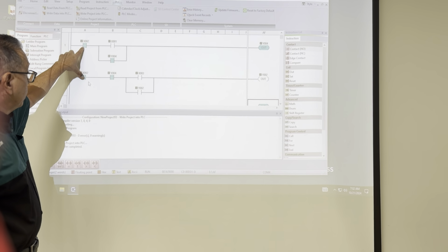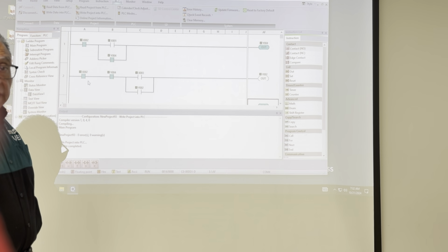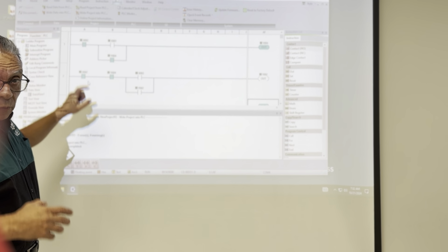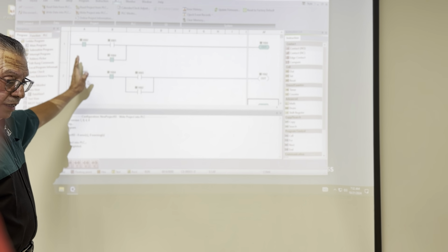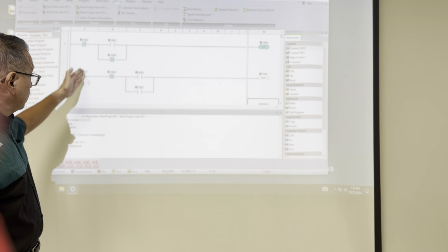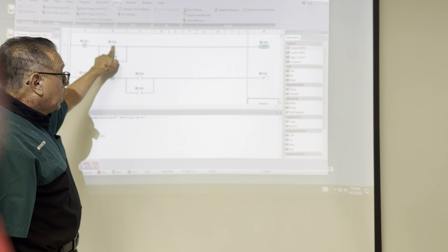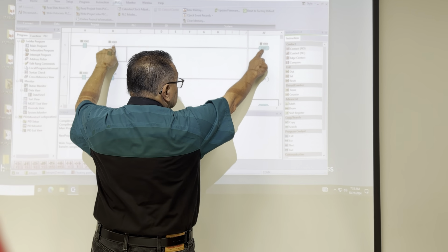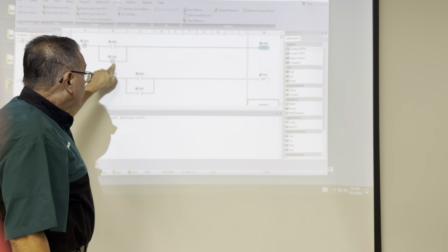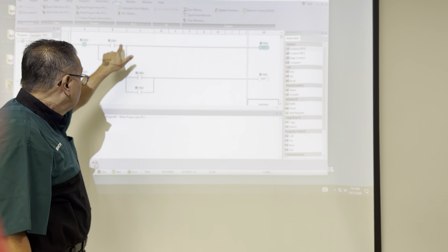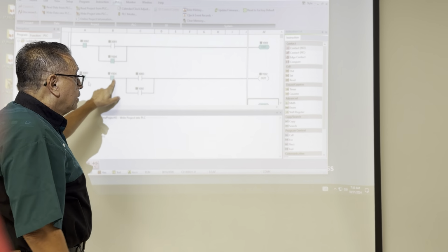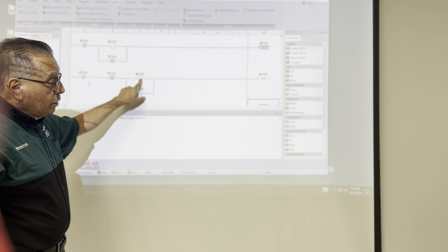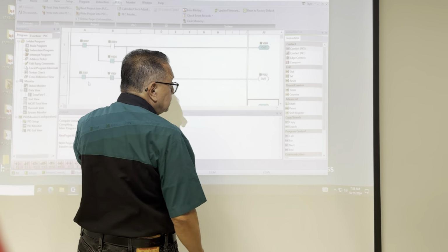I told you X002 is using negative logic, which means that when you see open here, in reality at the hardware level, when you start using the program, it's closed. So I already pressed X001, Y004 is true. This is holding or latching this, and then this one energizes this, just waiting to have an output on Y002.